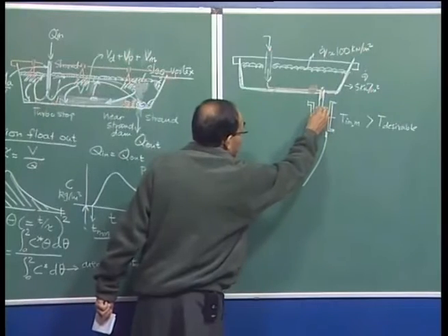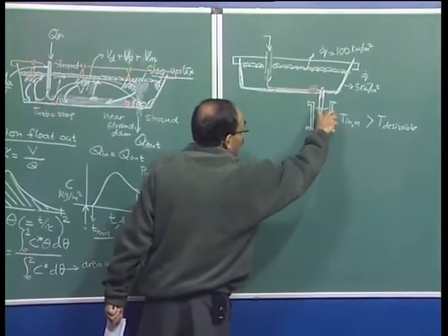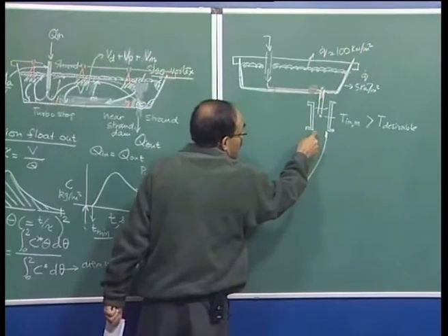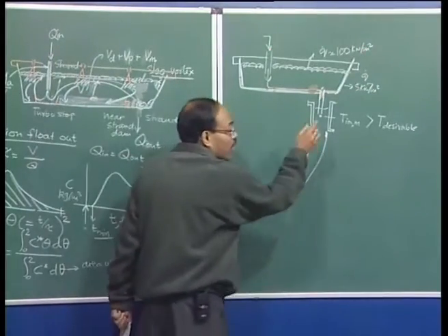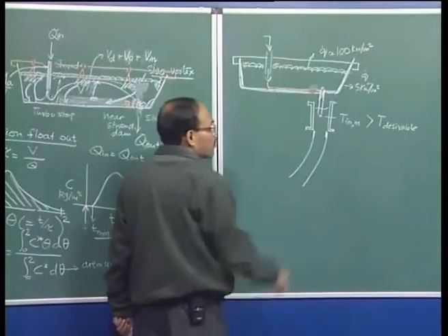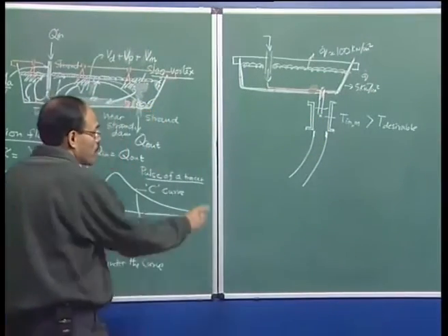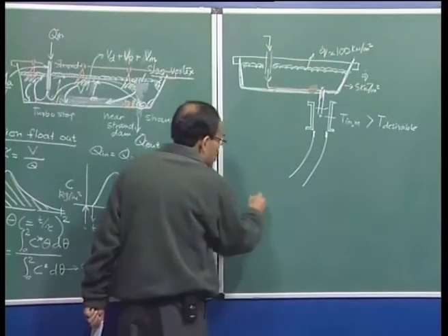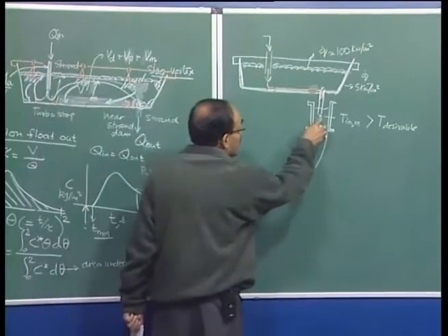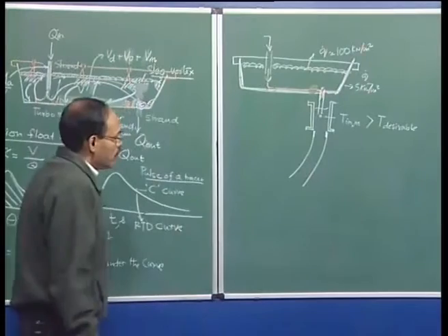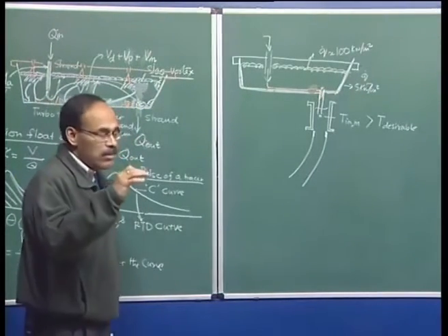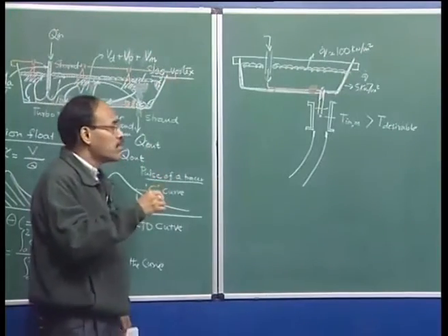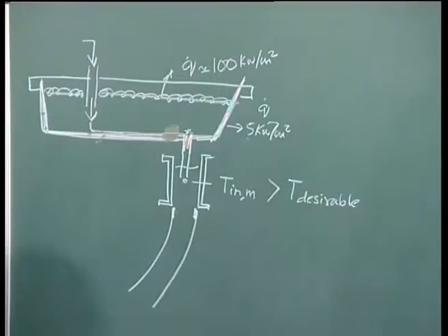Steel has an extremely large density. So, if we are talking of 1 meter, you can imagine that the ferrostatic pressure here is going to be tremendous, and if the shell is thin, and the thickness of the shell, I repeat again, is a function of the temperature itself. Also the cast composition and the cast's microstructure are intricately related to the temperature of the metal, and it is well known now that the smaller the superheat, the better the quality of the cast product. By the by, what is the definition of superheat?